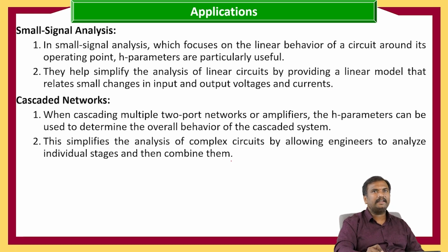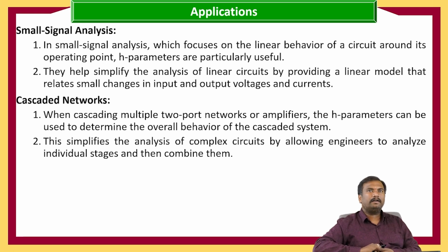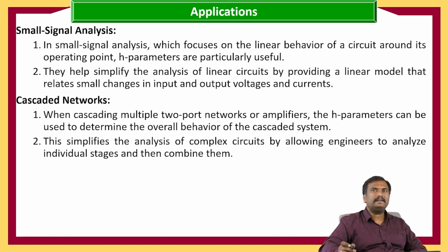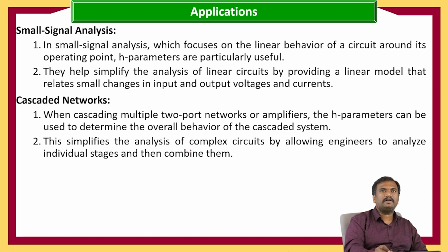And the next one is cascading networks. When cascading multiple two-port networks or amplifiers, the H parameters can be used to determine the overall behavior of the cascaded system. This simplifies the analysis of complex circuits by allowing engineers to analyze individual stages and then combine them.